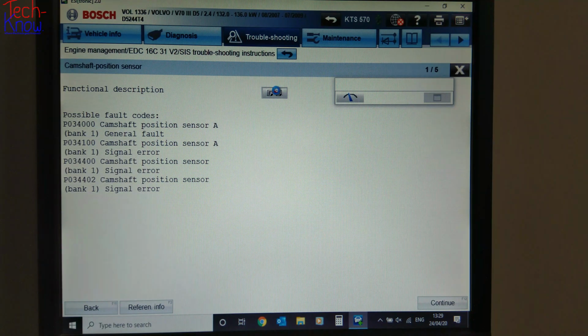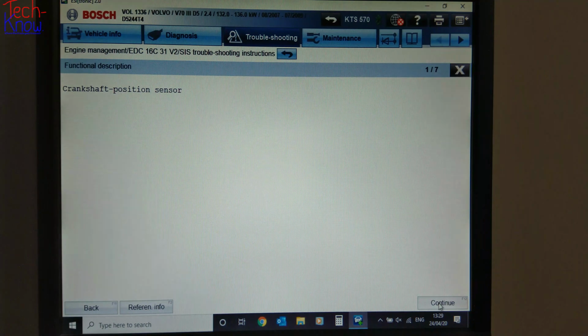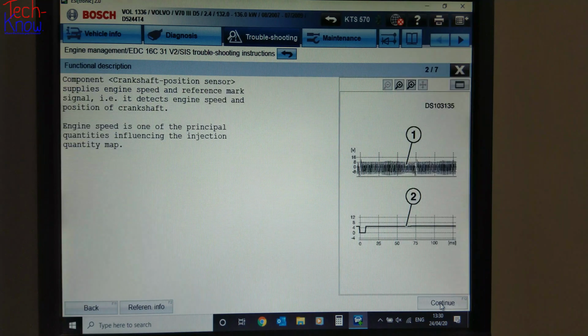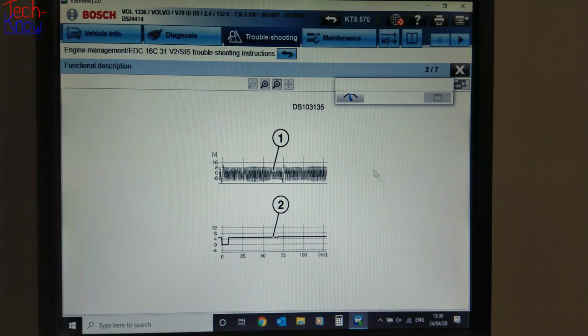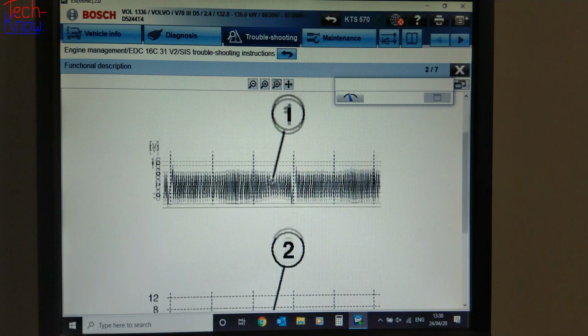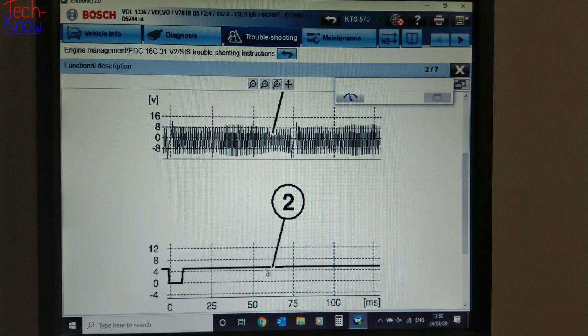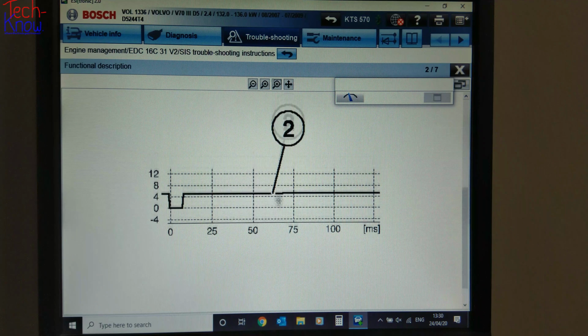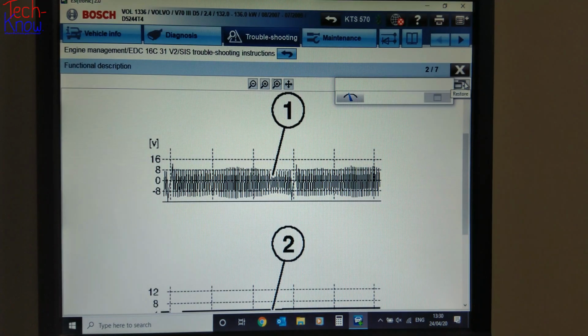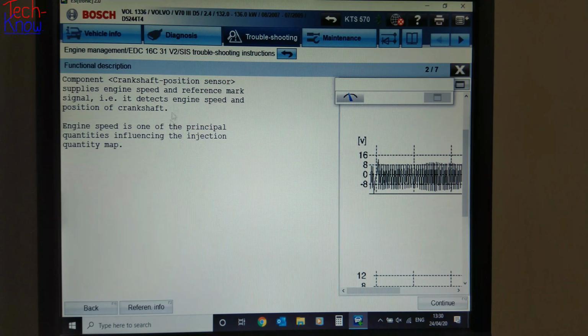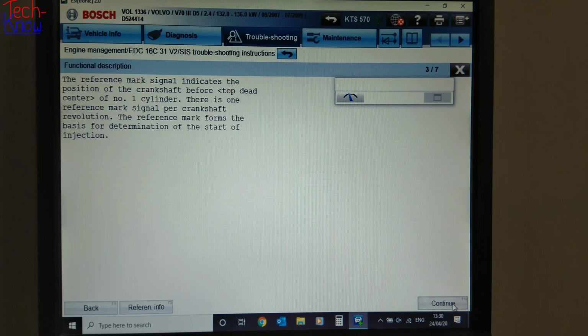The thing we were going to look at here is the electrical diagram. So this is the diagram for the engine management system. Continue. It warns you here that there are various different versions of this ECU, so the wiring may not be exactly right, but should be correct. Normally, optional connections are linked by a dashed line or a solid line down to the ECU component. Down the left-hand side we have our key showing what each individual component is, and on the right-hand side we have the actual diagram. With the diagram bigger, we can print it out using the print button at the top that we explored earlier on in the video.